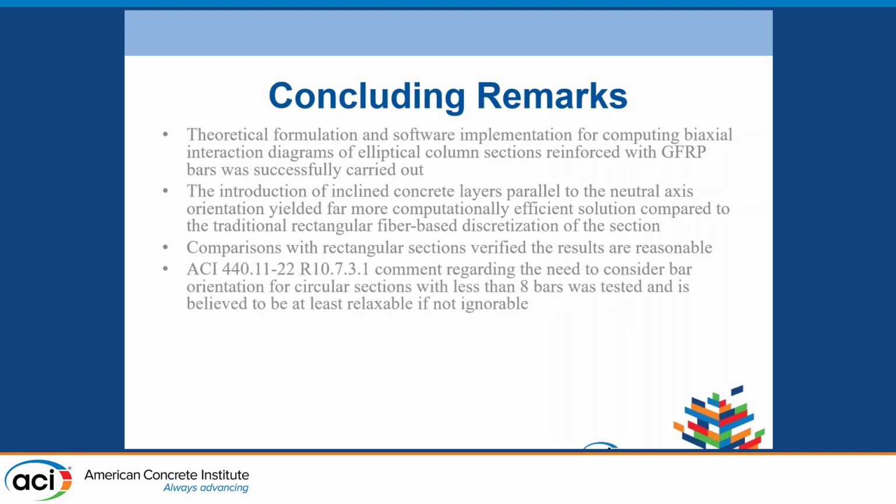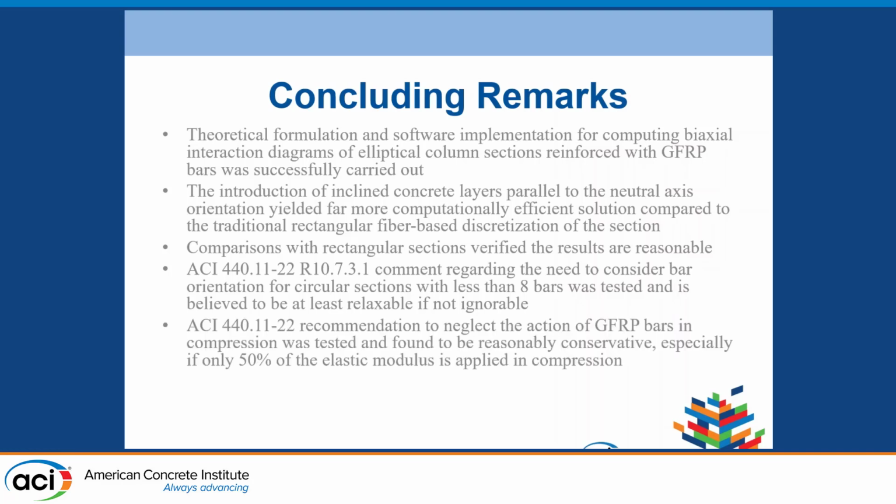We tested the ACI comment for circular sections, and we can safely conclude that this comment is at least relaxable to 6 rebars, if not ignorable, as I said, if we consider that the difference in 4 rebars is not that significant.